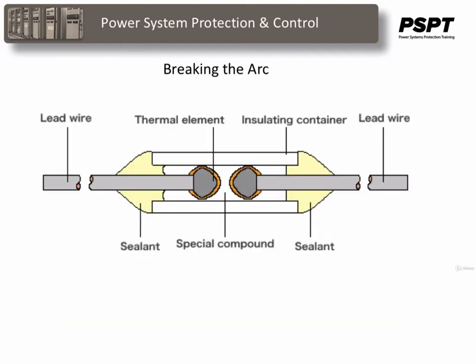The fuse element is constructed in various ways to use different methods for breaking the arc when it's interrupting the overload situation. Mechanical separation: essentially this is just a rapid separation of the parts of the fuse after it is melted. This is commonly accomplished by maintaining a spring tension on the fuse element. Arc treatment, in addition to the mechanical separation,